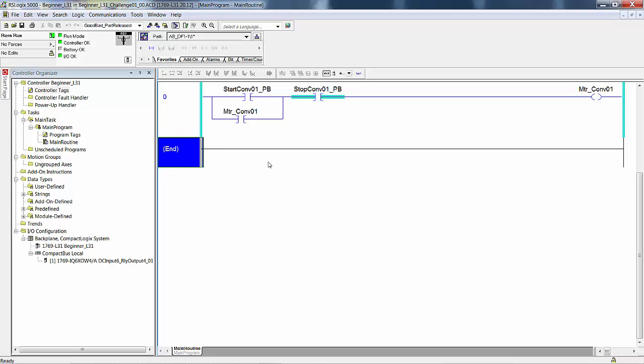This simulates pressing and holding down the normally open contacts of a momentary push button. So in this case, if we had a normally closed push button connected to an input module, if that button's not pushed, then that input is on. And if you're examining it with this tag, then this would be on. We're not aliased to any I/O now, so we had to toggle this on to simulate that condition.